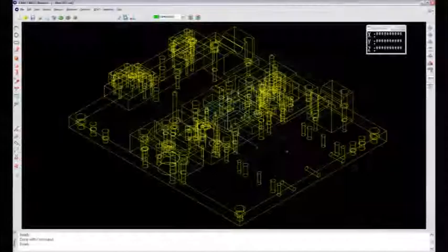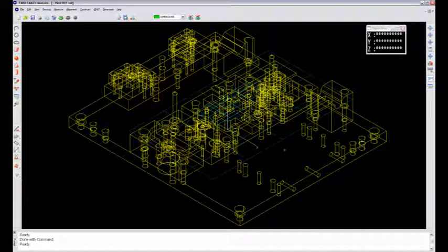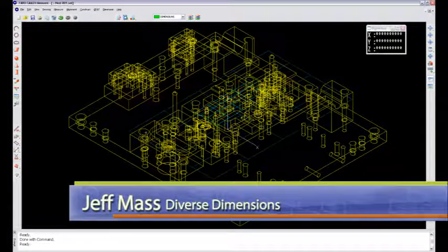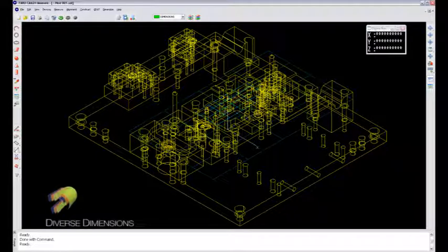I've got a fixture nest on my screen here in my SAT file. It's kind of hard to see if it's all wireframe like this, but I did some measurement on this fixture here. It's used in a manufacturing process to hold a shifting mechanism for an automotive application. And what I've got are surface points on various locations here on some datum pads and rests.